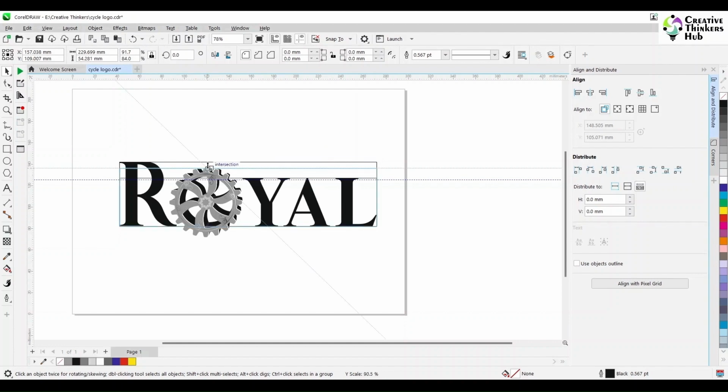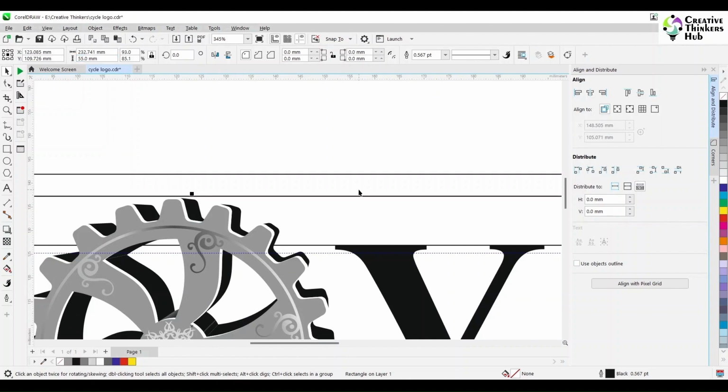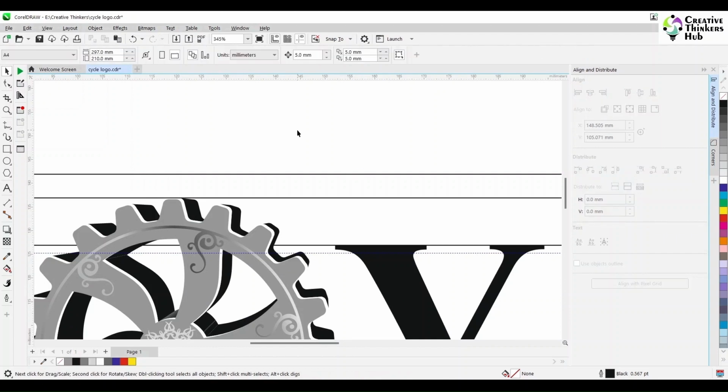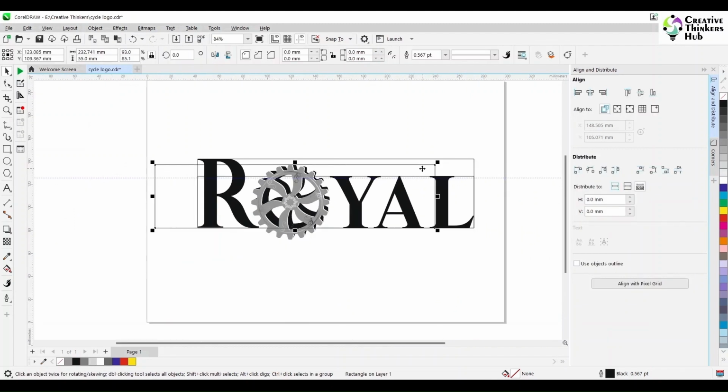Then now what we do is, now we'll work on the gear. So you keep this here, let this be at 55. Okay, and base align it. So we know our gear is 55 mm on top and then 10 mm down. So now we work on the remaining 10 mm also.